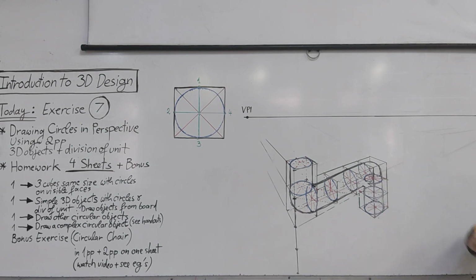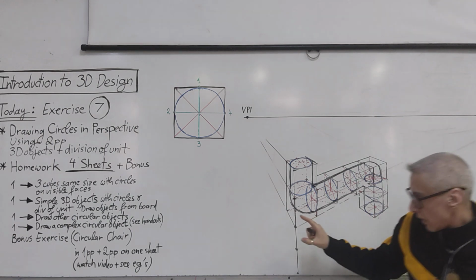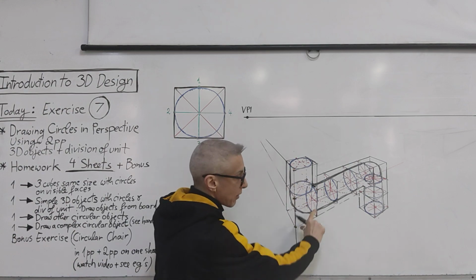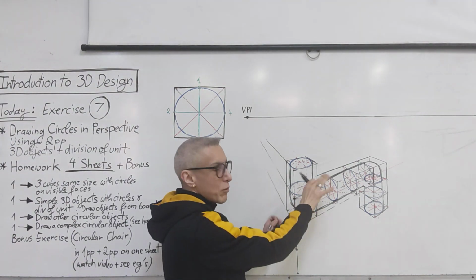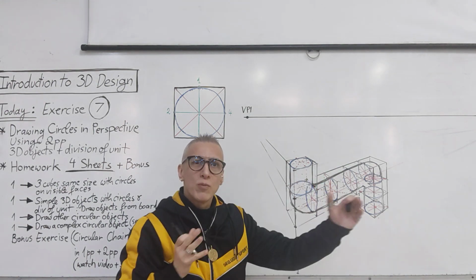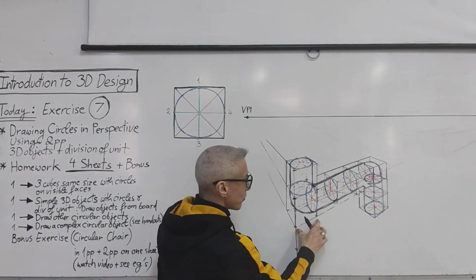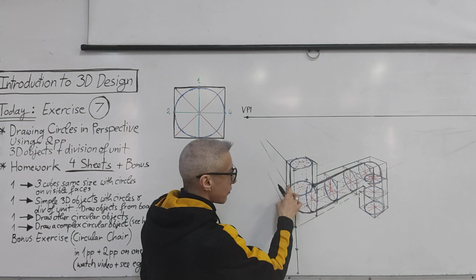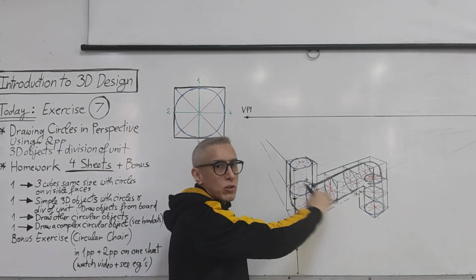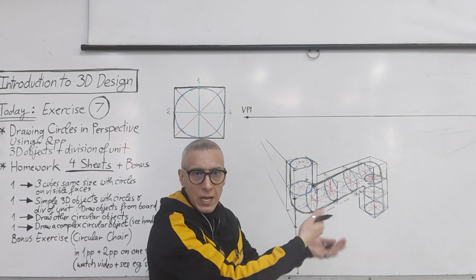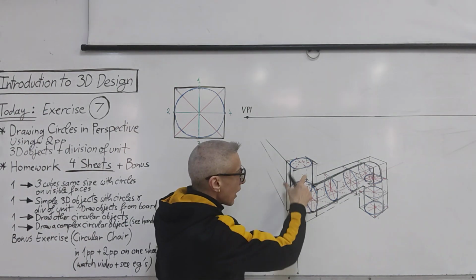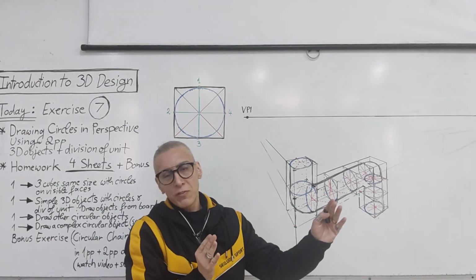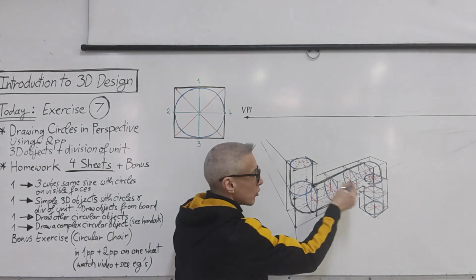Now, the problem is if you haven't measured here correctly, for example, I said 5 centimeter, 5, 5, 5. If you haven't done that correctly, some of the objects will not look correct, some of them will be too small or too big and not fit. Now, also, because you're drawing by estimation, if you put this side, for example, this is not a cube, too much, too little, then you divide it wrongly. Any mistake on the way and the accuracy, after when you connect these, they will not fit perfectly. You will see one circle too big, one circle too small, and all of these problems.